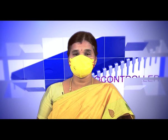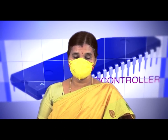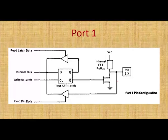Port 1 is a simple I/O port, where the 8 signals or 8 pins can be used as either input or output. By using this configuration we can send our own data to the external device. Internally, VCC is connected through a pull-up resistor, so it always has 5 volts, or logic 1.